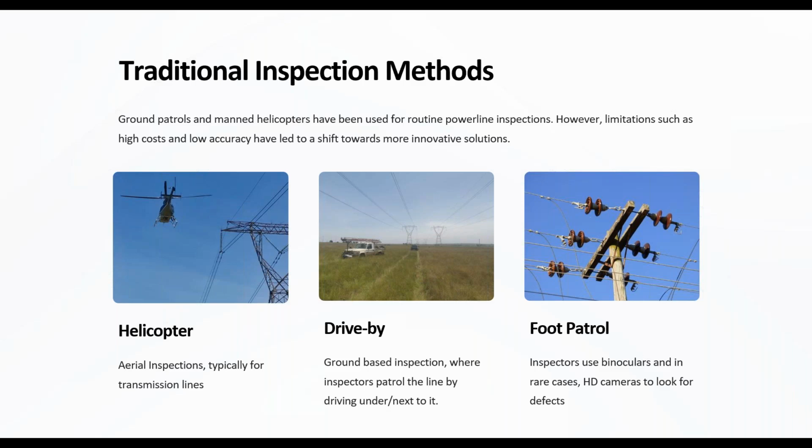We also have a camera which is a UV lens, ultraviolet, yes. That is designed to pick up corona issues, and also a normal visual still image and video that we use to see all the visual defects while the helicopter is flying along or over the overhead line. So the inspector sitting there will be able to control that gimbal, look at those issues and capture those problematic areas that they pick up.